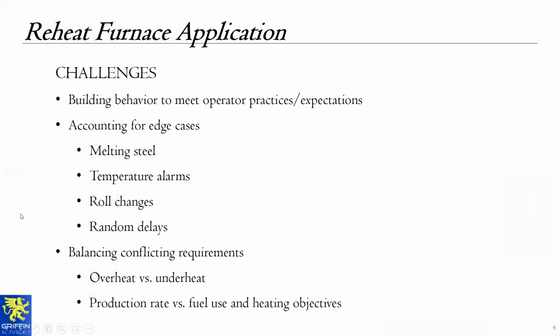Because normally I would slow things down to make sure that every piece of slab is up to temperature fully by the time it reaches the extract zone. And also how to handle temperatures during random delays. When a delay comes, you can use it as catch-up time first, and then you're sitting there in maintenance mode.